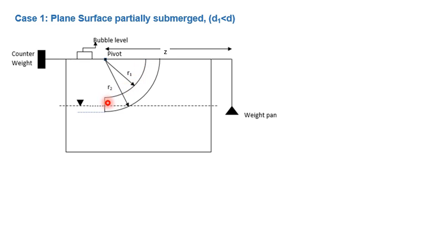And this is a toroid, which is a quarter part of a donut, you can say, and the distance from this pivot point, or you can say radius of curvature for the inner part is R1 and for the outer it is R2. So R2 minus R1 will basically give us the thickness of this toroid or the height of this vertical surface. And only this much part of the toroid which is inside the water is going to experience the hydrostatic force.